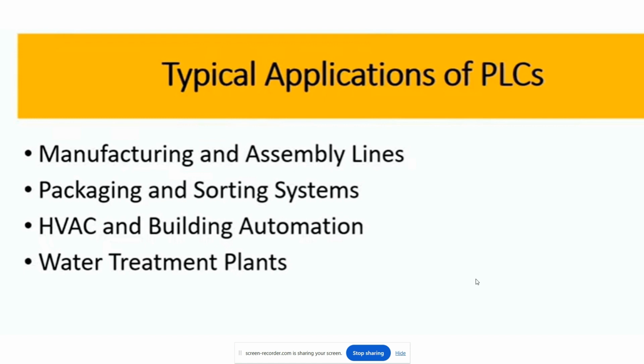So HVAC, this is heating, ventilation and air conditioning. For example, controlling the climate in malls, you find it makes sure the temperature is maintained, let's say at 24 or 25, depending on the weather outside. If the outside temperature is 26, it will do monitoring, it will do cooling to make sure the temperature is down to 24. If the temperature is down, let's say 20, it will raise it up to 24. So according to the set point and present value.